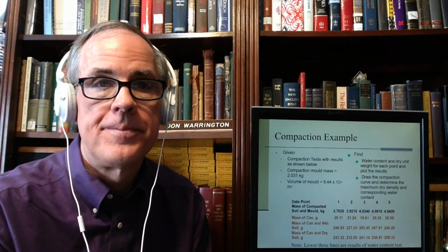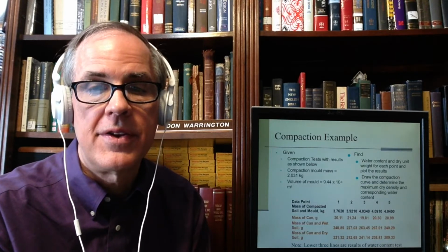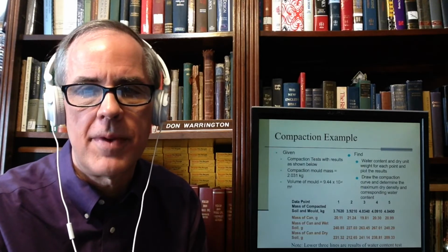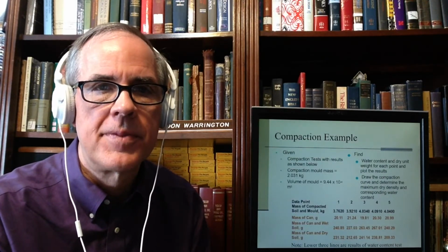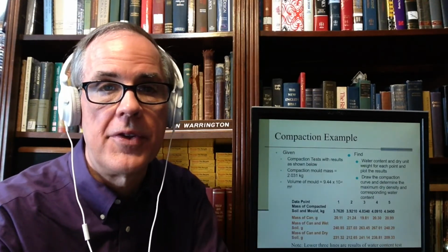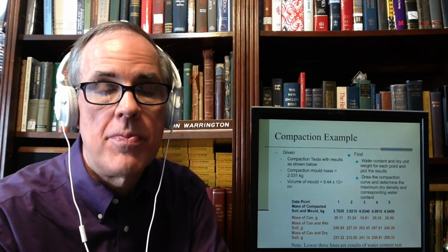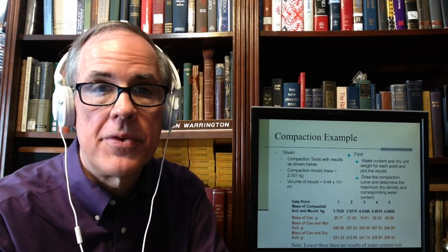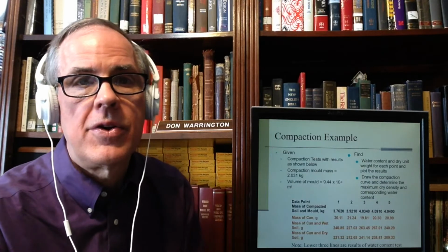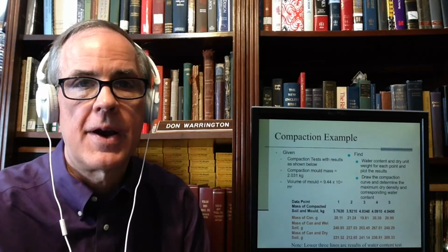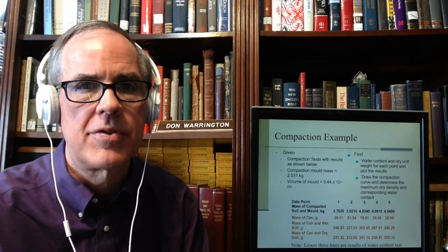In your lecture course, most lecture-related problems will dispense with the tare weight. You remember with a water content test, you start out by measuring the weight of the tare, or the little can that you put the soil sample in. Then you put the soil sample in and you weigh them together. Then you put the soil sample in the oven, and here at UTC we use a conventional oven. It's possible to do it in the microwave, but it takes a little more skill not to screw the sample up.